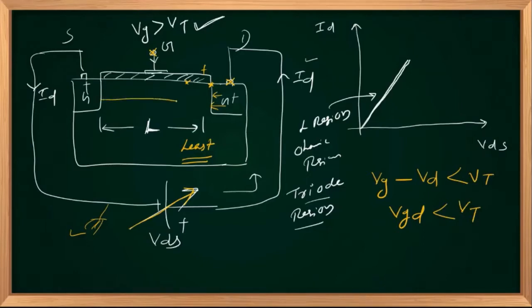All points will have the same potential, so the potential difference between source and drain is the same. So we'll have an N channel as earlier, which should constitute a current. And due to that current, if VDS is sufficiently large, as we discussed earlier, this channel will move towards the source end.